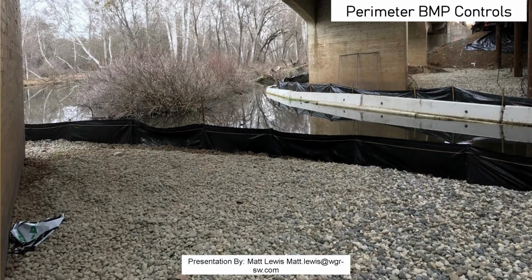The key thing with silt fence, like with fiber roll, is you want to make sure it's keyed in. A little trench is dug out, it's partially buried, usually about 6 inches or so, then covered up. Also, with silt fence, you'll want the stake on the opposite side of where the flow is coming from, because if you have it on the side the flow is coming from, it's just stapled in, so it will get pulled off.